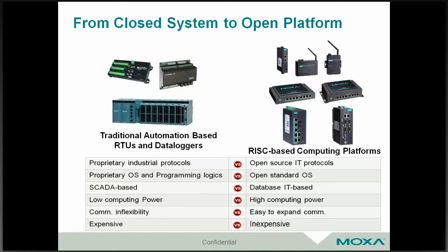If you put that back to the RTU or POC, the driver is simply not there. So if in the future 5G communication capability comes up, very likely you again have to swap out that external communication router. You're not able to use that generically on your RTU or POC. But on a computer, you can use USB or the standard mini PCIe for that wireless upgrade, right?